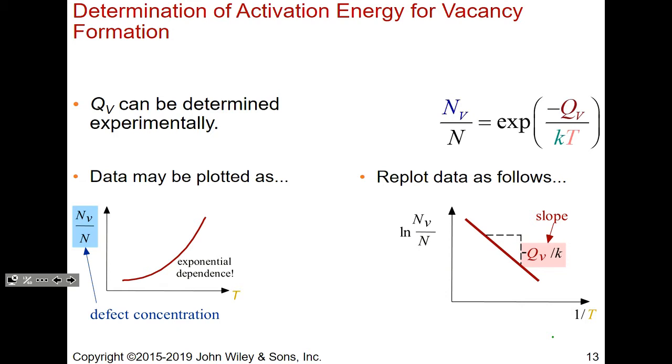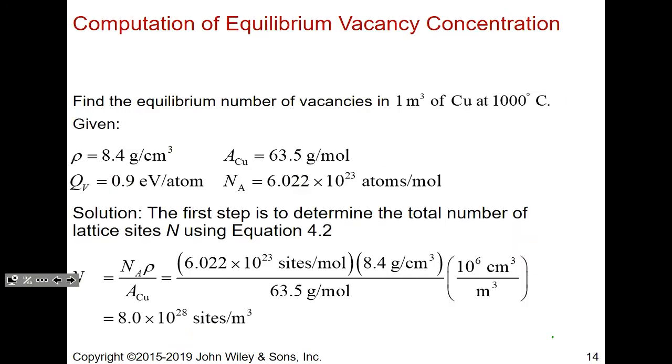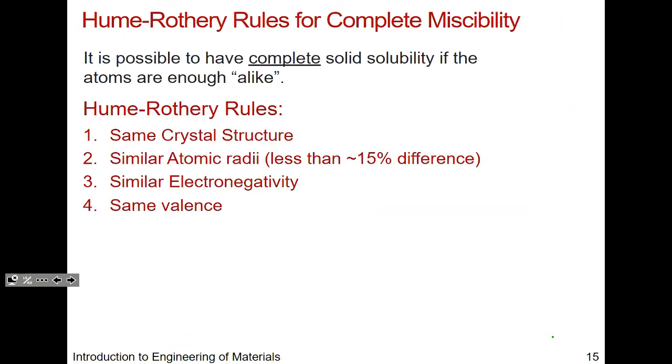Atoms are now able to vibrate a whole lot more, and they can have enough energy to hop to another site. And they can keep on hopping to the point where they can hop to the edge of the material. And that could actually expand your lattice constant quite a bit, both due to thermal expansion, but also due to vacancies that are being generated. Okay, so that's where we left off last time, appreciating the thermal activation processes of vacancy formation and the Arrhenius, and manipulating the Arrhenius equation.